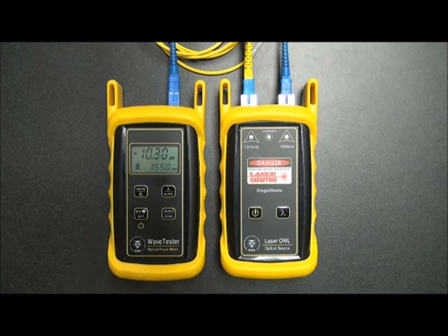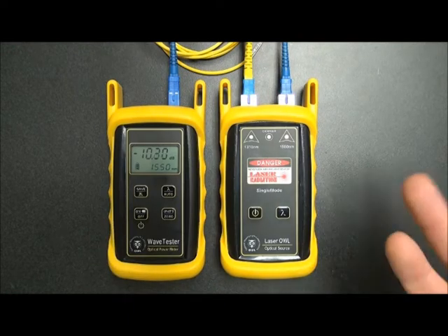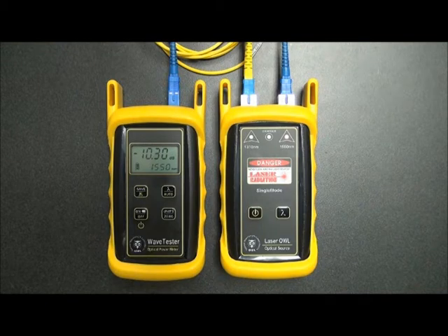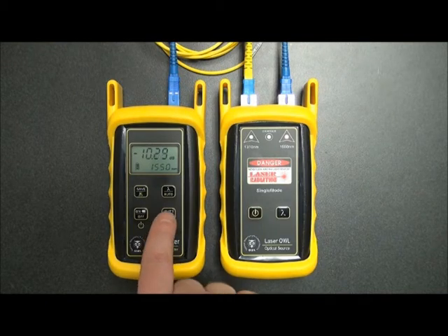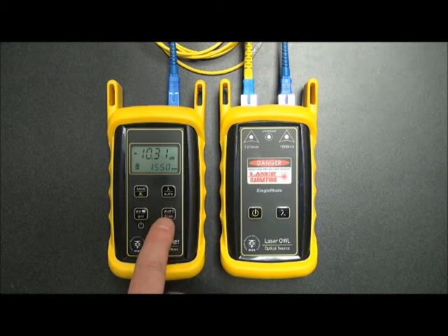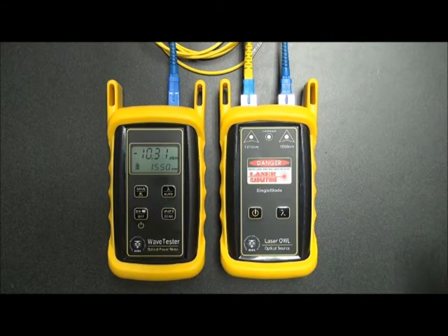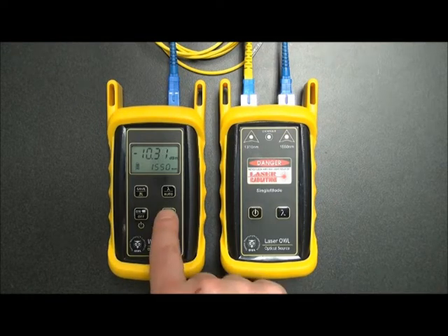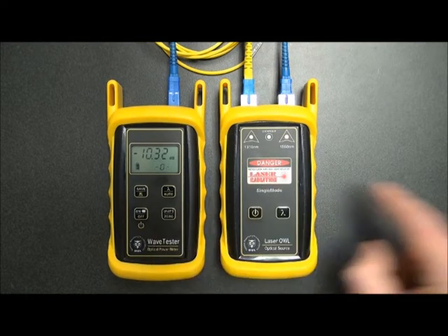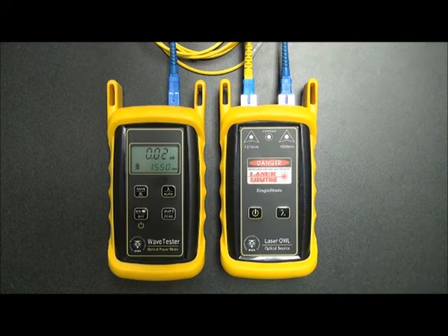Now, in order to check to see if the patch cable is good or not, we have to be in dBm mode. So we have to change this back to dBm units by pressing the units button. Okay, and as you can see, it says minus 10.3 roughly. This patch cable is also okay to use for our test. So to zero out this equipment, we simply press and hold the unit 0 button to zero it out. And as you can see, we have a reference level of around 0 dB. What this means is that our equipment has been zeroed.